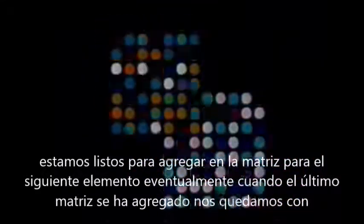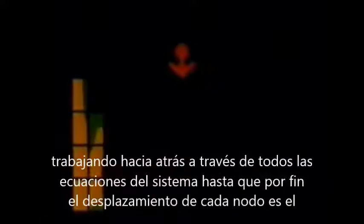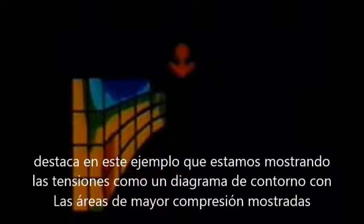Eventually, when the last matrix has been added, we're left with the solution for a single node. We can now use this result rather like a key, working backwards through all the equations of the system until at last the displacement of every node is obtained. From these results, we can quickly calculate the corresponding stresses.